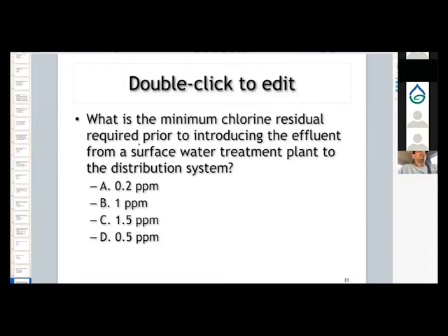Depending on the system, I can't even imagine a system wanting to do a 0.2, and that would be the very minimum. The chlorine residual that we put out into the system right now, we use chloramines at East Bay MUD, so we're measuring total chlorine. We put out about 3.5 milligrams per liter. In free chlorinated systems, they put out much less, about 1.5 parts per million, because it's free chlorine. It's a lot stronger, and it's a lot more stable at the lower strength, or residual.